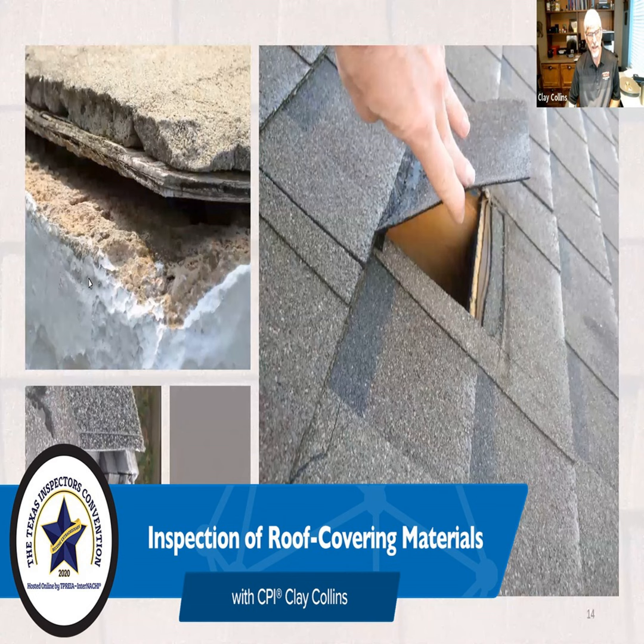I personally go on the roof first, but I have also found that there have been times I've had to go back on the roof. But my personal approach is go on the roof first, look for those areas that I suspect might leak, and then I'm able to track down in the attic or on the ceilings whether that's in fact come through. I'm also able to explain, because the client will not go on the roof with me, I'm able to go inside and say, I see a stain here, and that corresponds with a location of repair to the roof. It's not wet right now, therefore the repair may have been adequate.